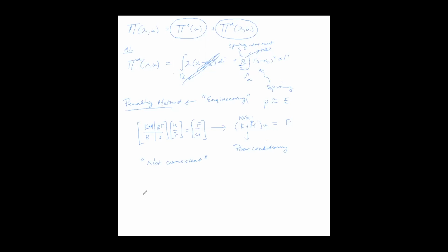So the full augmented Lagrangian method is really nice because you'll get exact enforcement of constraints. And because you have a force associated with the Lagrange multiplier, the penalty term that you give is almost problem independent, meaning that it can be of a fairly small value.